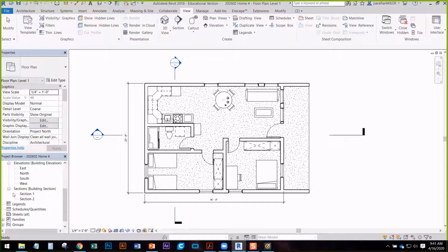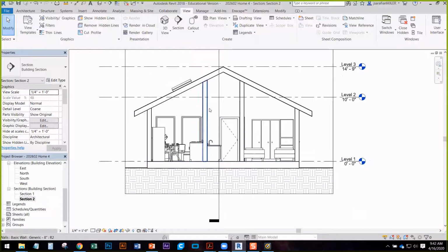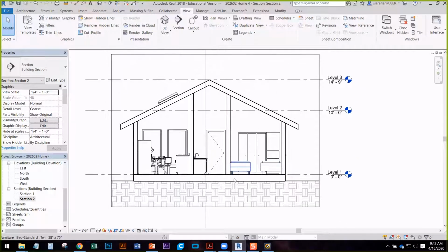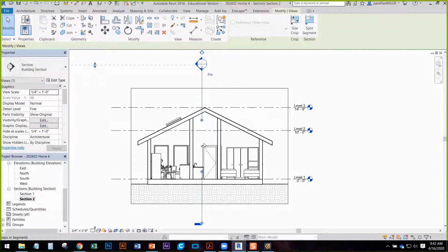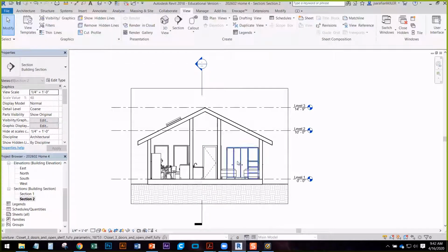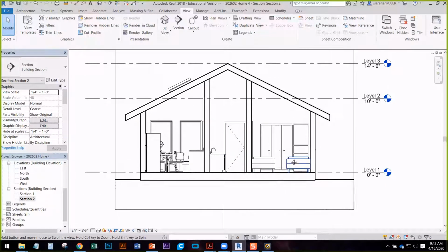All right, so now to look at the view, we can either go down in our project browser. You'll see that there's a new tab that emerges if you haven't drawn these yet, and you'll see the section that we just drew is here. So I can either double click on that or double click on the section itself. So here we're seeing a section cutting through the ADU. Again, this is showing the section cutting in the other direction, so that we can click on the lightning bolt, open that up as well. Okay, so we don't have that line cutting through the drawing.